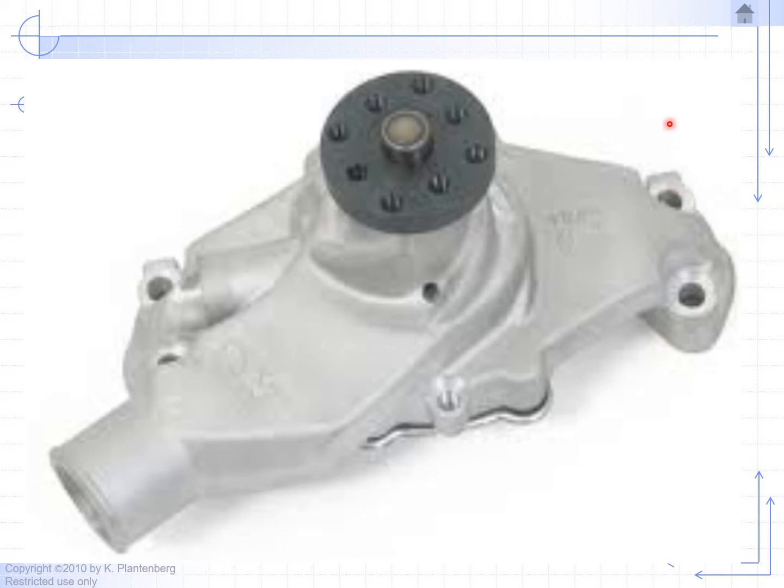That'll guarantee that the bolt will go in perpendicular. When you bolt it onto the engine block, you don't want this surface to be at a different angle, causing stress on the head of the bolt and causing a twist which may snap the head off of the bolt. So here we want parallelism between the counterbore holes and the base, and it'll be mounted onto the front of an engine block. Okay, next slide.